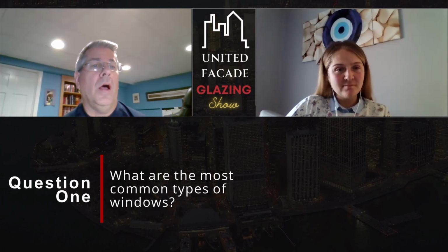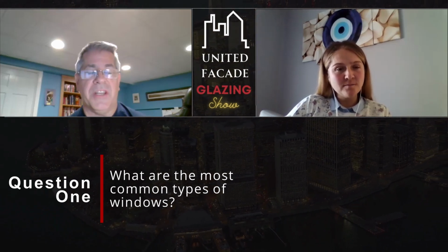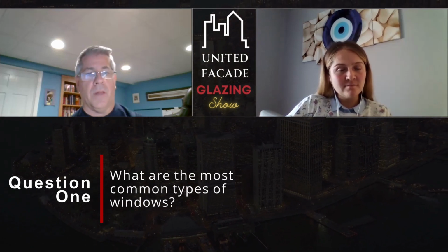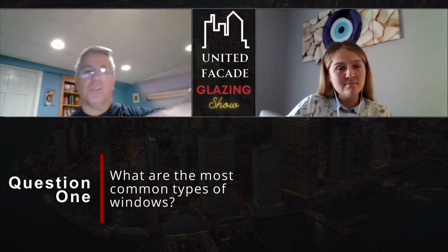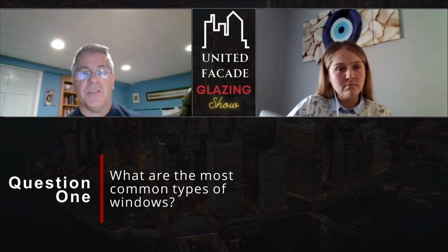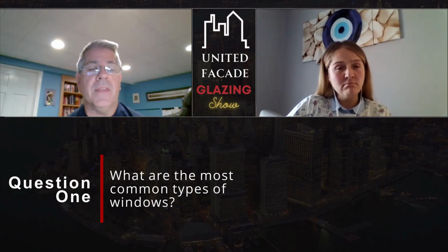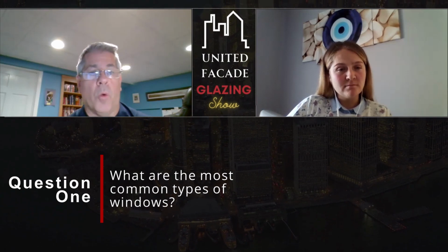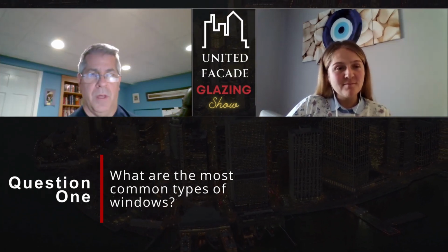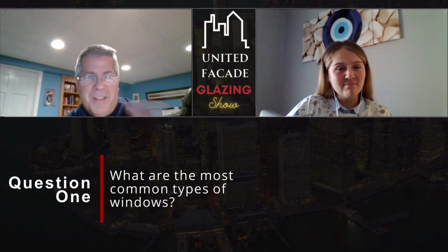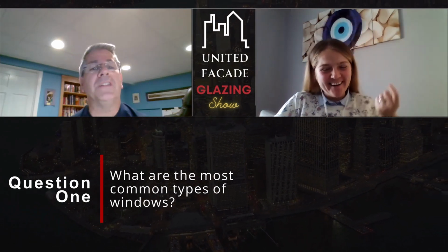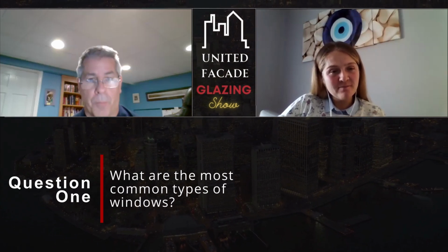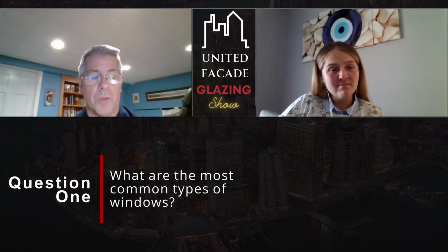Additionally, at least in these larger cities, you'll have requirements that the window itself, even though what you and I are thinking of, you can open a casement window and it could open almost the whole way, you can open 90 degrees to the frame itself. In these larger cities, there are limit devices that you have to put on these windows that only allow them to open 4 inches. You say, hey, 4 inches is nothing. Yeah, it's really small. Well, it's enough to let air get into the building so you can get a fresh air exchange inside your apartment, your office, or whatever room you're in.